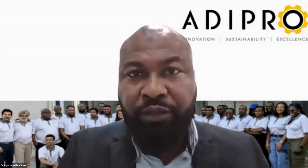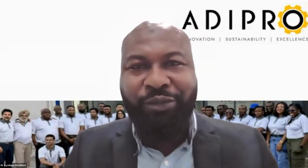Interesting question, because in the beginning I mentioned something about the sulfur in the fuels we have here, and also the amount of carbon in the fuels that we use. Africa is very inconsistent. If you're using a high sulfur fuel today in your engine, you're going to have more active sulfur radicals in your oil when it is operational. When it heats up, the sulfur becomes active, and this can actually attack the metal parts of your engine.